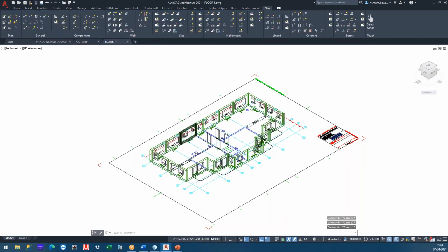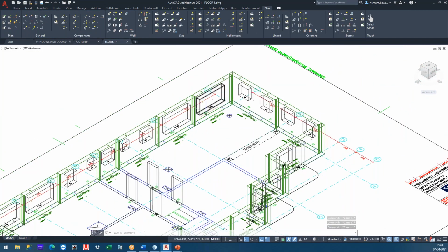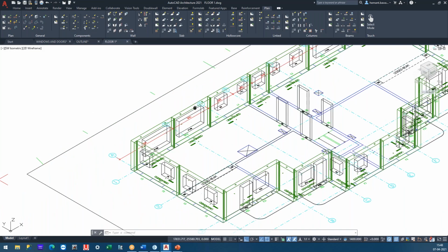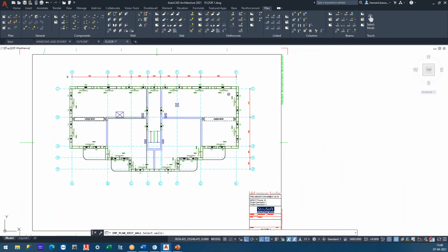Here, as you can see, the openings are marked as black currently. That is because we have added them into the model, but they are yet to be linked to the walls. So what we will do is, again, shifting to the top view, we'll edit all of the walls, and we'll add these openings to this. And the program is asking me if I would like to update placing of the lifts and the bracing anchors. And yes, of course, I would like to update them.